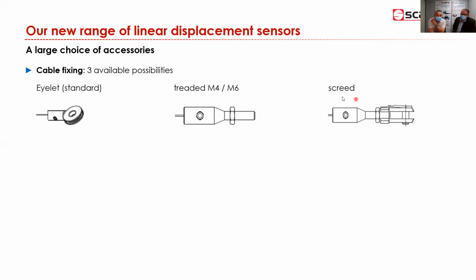Another principle is a clevis. There is a system where we can unlock this part and the axle comes out. You can put the steel system inside, put the axle back, and lock the system to be sure that everything stays in the right position, and there is no risk that it drops for whatever reason.